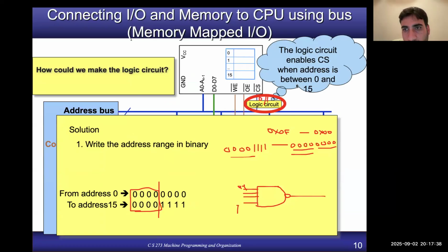Put a NOT gate, yeah, just invert them, right? Because I know that they will never change their values. Their values will always be 0, right? I know it. So I can simply put a NOT gate on the input, which I can indicate by putting a bubble here. If I am putting a bubble here, it means just put a NOT gate. So this is what is done here.